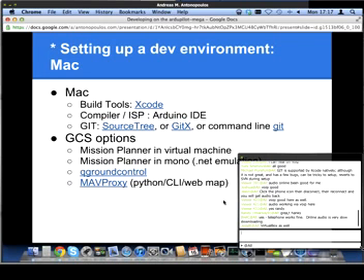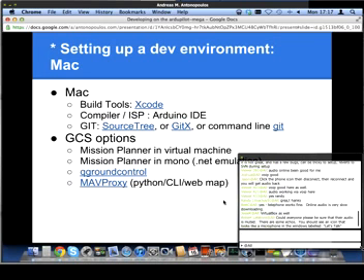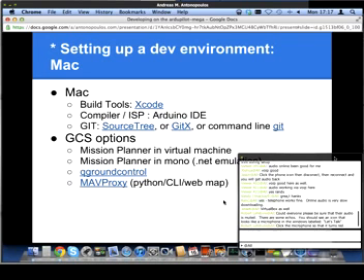And finally, my favorite, the completely underutilized and totally deserving of more publicity, MAVProxy, which started out as a proxy for MAVLink, but is now a very sophisticated Python-based cross-platform command line interface for ground control systems, and has some sophisticated modules with graphical capabilities, including a moving HTML map.